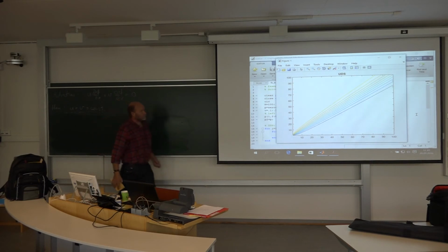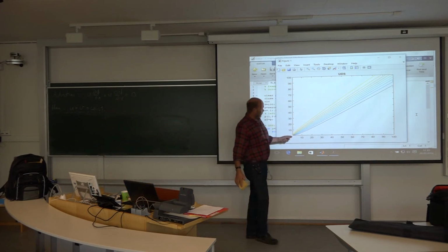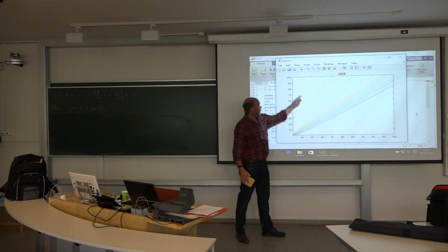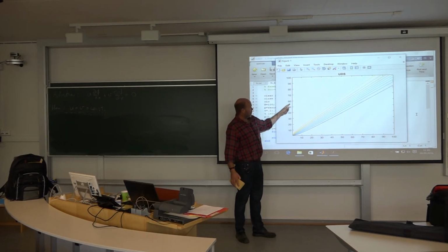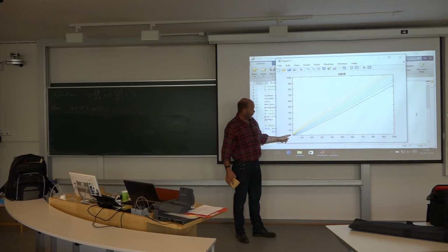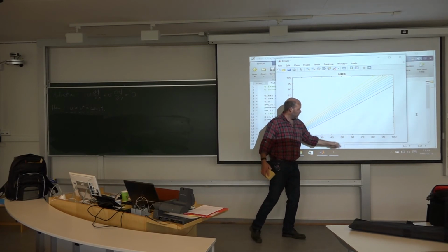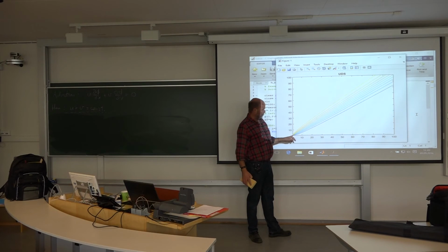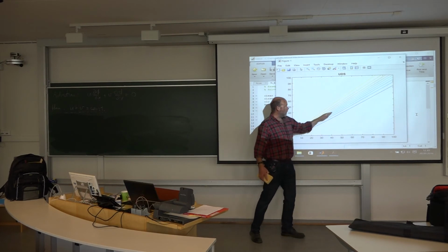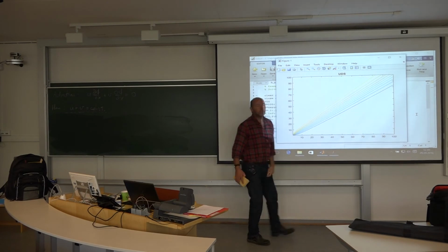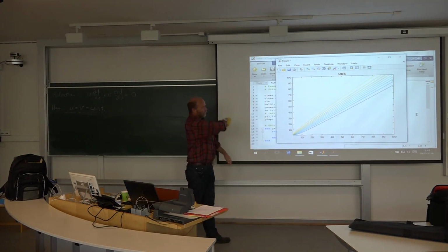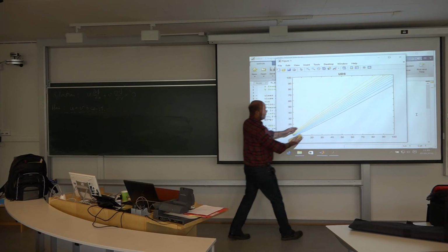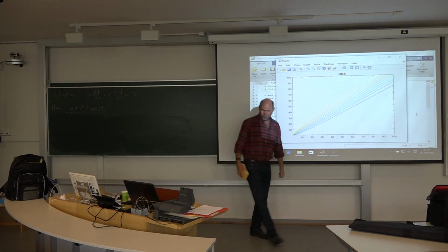You see this smearing out of the value phi. I mean, here we now send in phi equals 1 on this boundary, phi equals 0 here. So we have a sudden jump. And this sudden jump should be sustained alongside this 45-degree angle. But you see the effect has been smeared out over a substantial region.